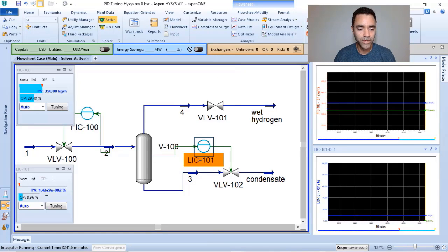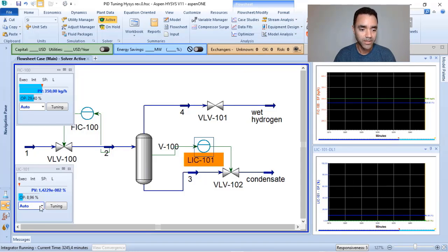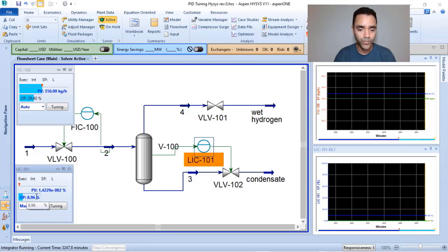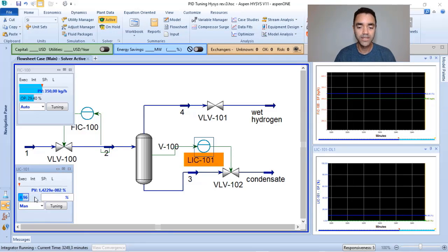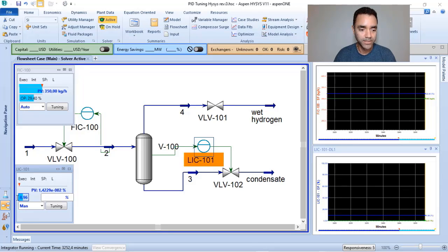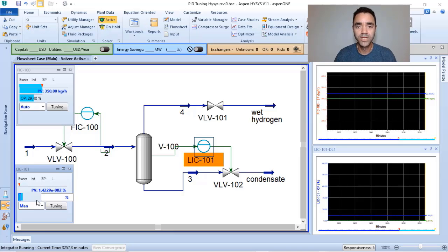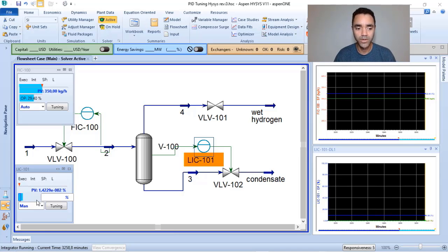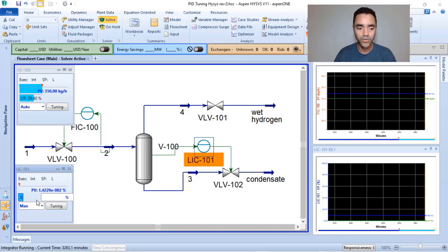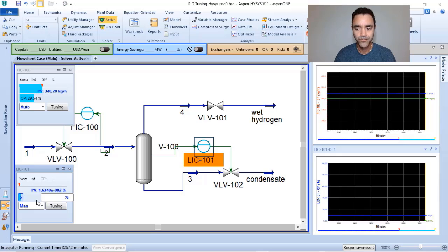So what I can do here to have some kind of level in the system is to put it on manual, and this opening is too big because I'm not adjusting the valve based on the amount of liquid that is going into my process. So instead of having 8, almost 9, I will consider 5% of opening.